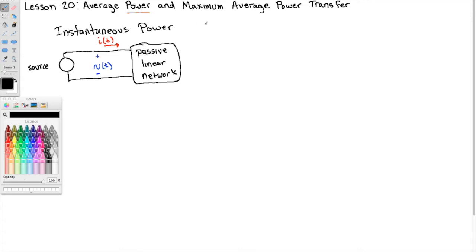Now, in DC circuits, we said the power is I times V. And this is the definition of electric power. You need some I, you need some V. And power is I times V, and this has units of watts. Well, it won't surprise you then in AC, so this is at DC, that this must be true then at every slice of time now.